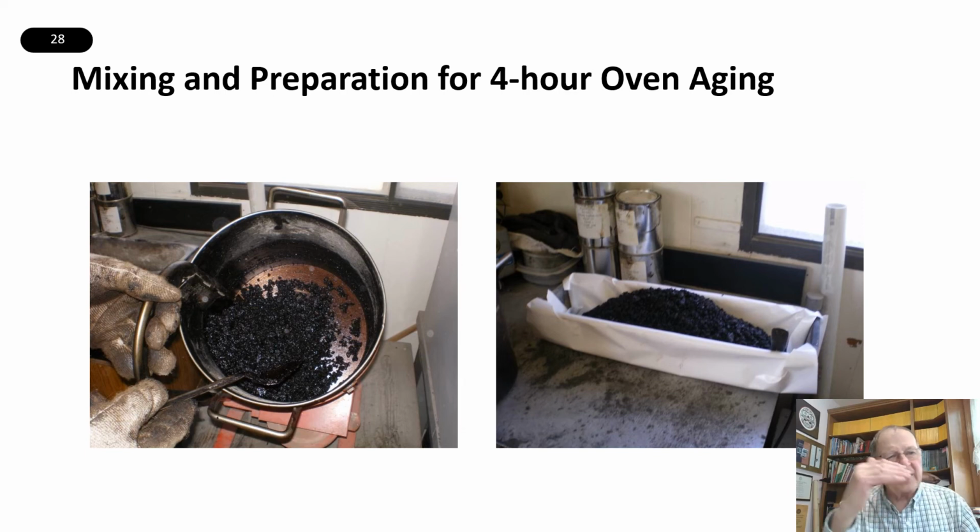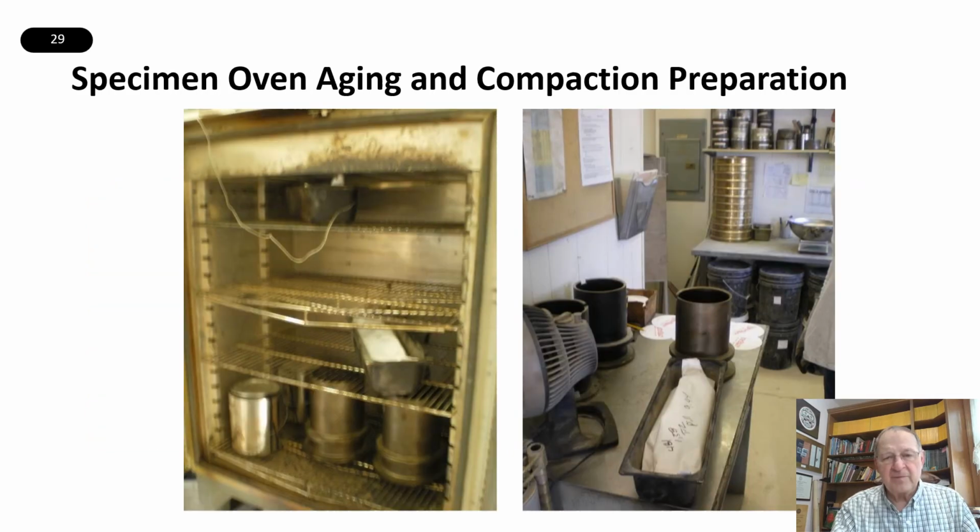The asphalt binder absorption will decrease with time. By the time we get to 4 hours, it's mostly stabilized. It can still increase a little bit, but not that much. So 4 hours is what INDOT requires the mix design be.